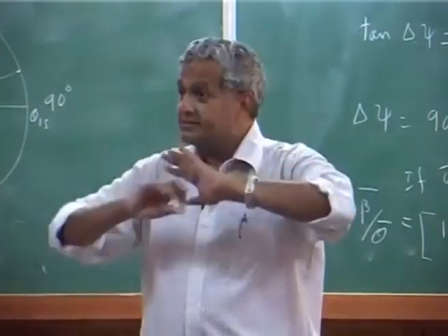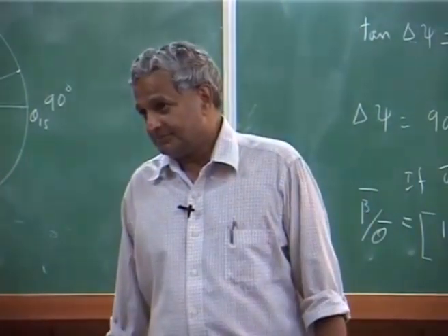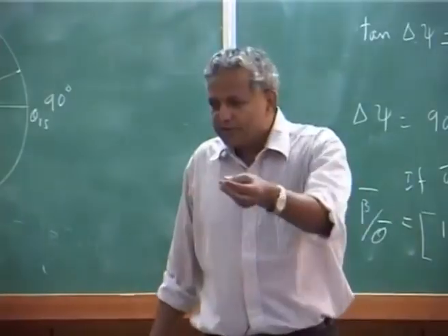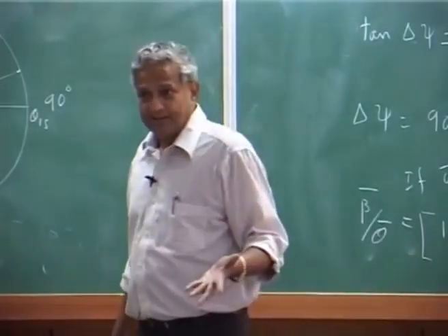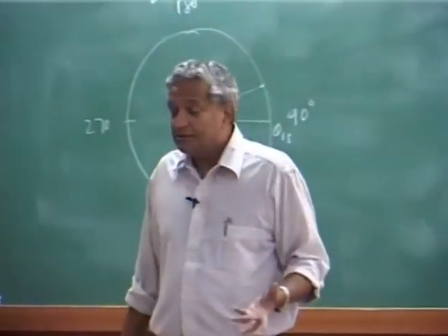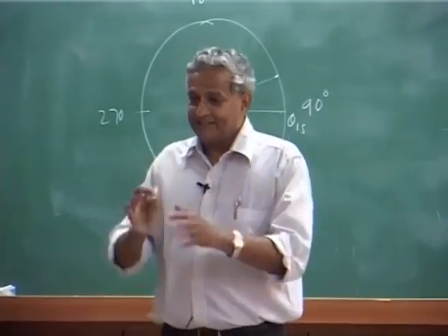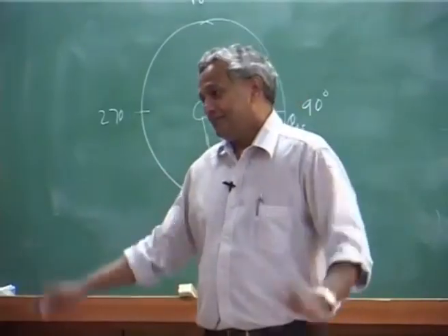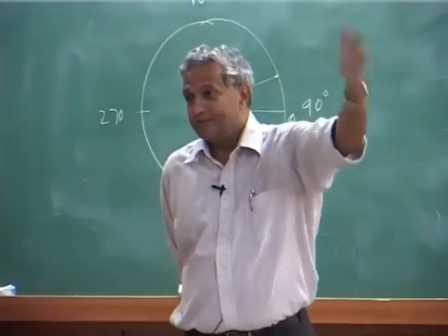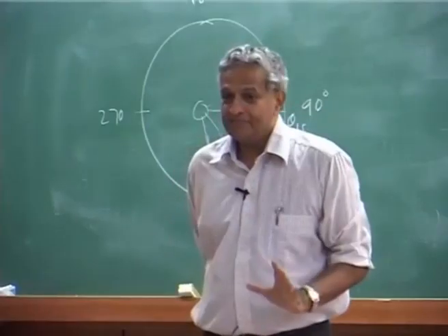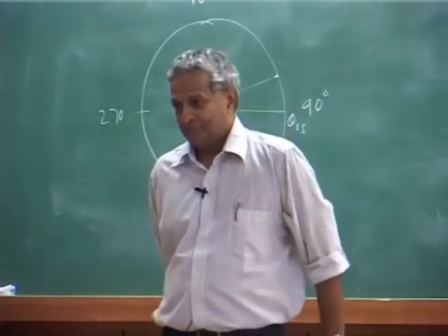You have to analyze the full helicopter. So, industry, for ease of understanding, you can do a little bit of decoupling, but otherwise it is not possible to decouple the full longitudinal lateral degrees of freedom. So, you have to solve the full 6 degrees of freedom, all coupled in the flight dynamics.